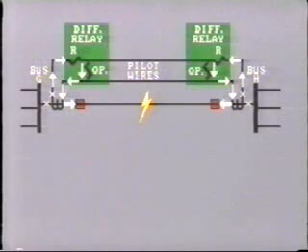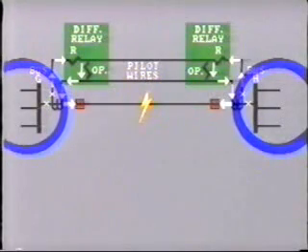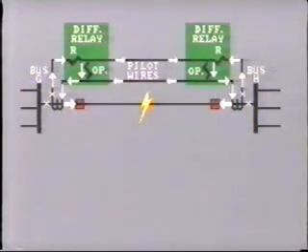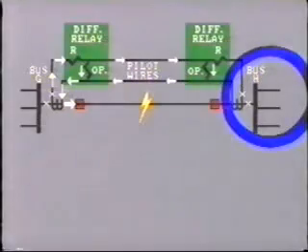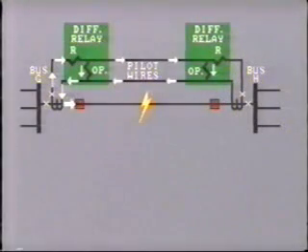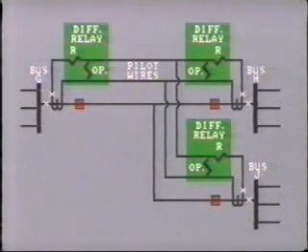In most circumstances, the magnitude of current feeding in from each end of the line is not identical. The exact value depends upon the location of the fault and also the amount of fault current available from the source at each end. For this reason, a small amount of balancing current will still flow through the pilot wires. An extreme case would be when there is no inflow of current from one end, say from bus H. All the fault current is now fed from the source at bus G. The CT secondary current will now flow along the pilot wires and pass through the operating coils of both relays. So it will still achieve the protection scheme's main objective, that is, to trip the breakers at both ends of the line simultaneously. This type of arrangement can be extended to include a third terminal, like this.